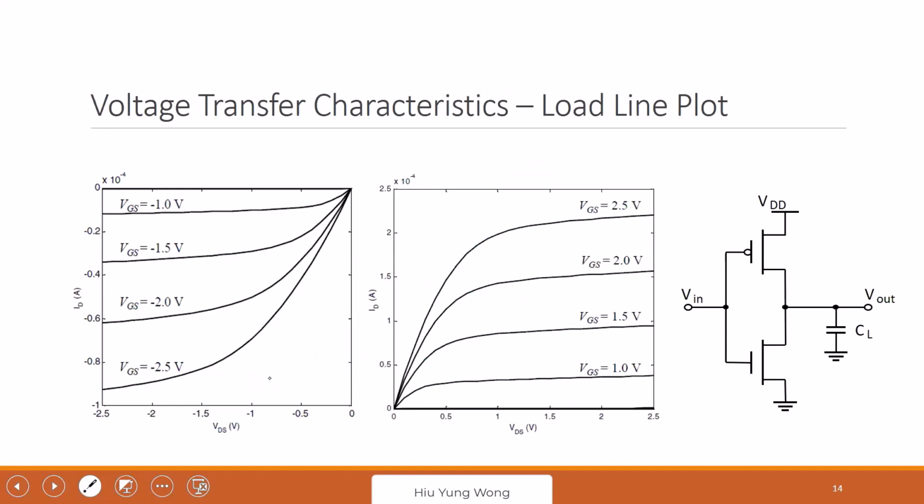Finding the VTC would be good. I like this approach. This is instructive and helps you understand an inverter better. So how do we find the VTC? You can solve the equation. You can do SPICE. But there's one thing called the load line approach.